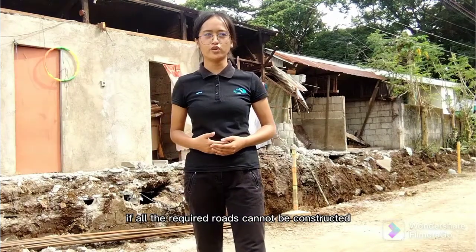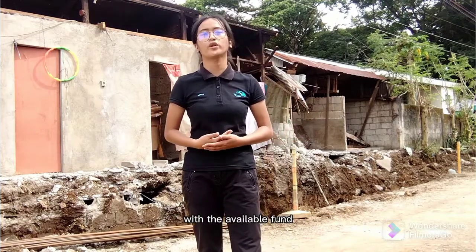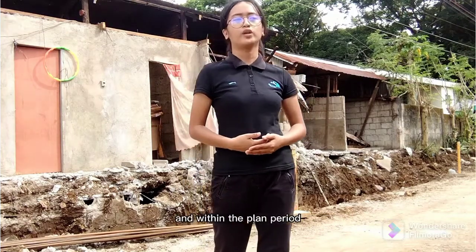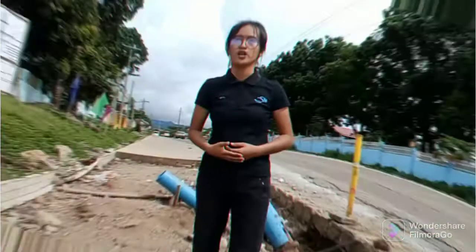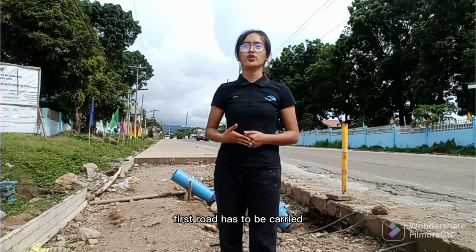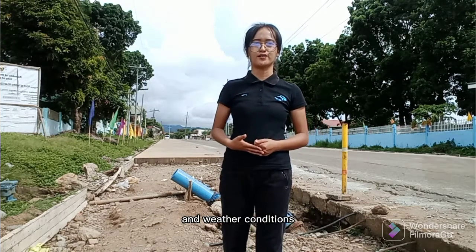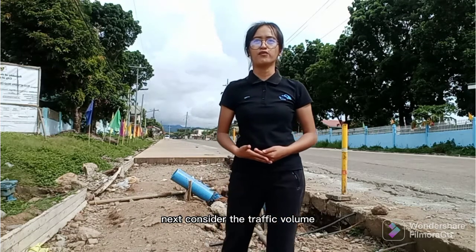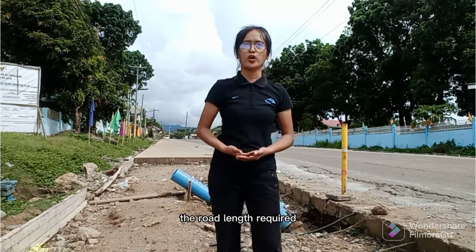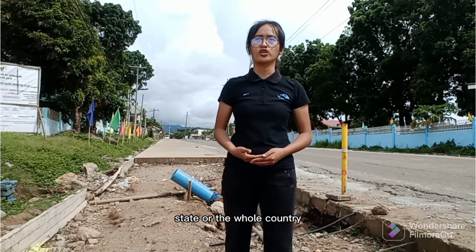If all the required roads cannot be constructed, the most important should be constructed first with the available plan and within the plan period. So, these are the following important notes to remember. First, roads have to be carried out according to the different season and weather conditions. Next, consider the traffic volume, road transported, location, function, etc. The road length required for an area, it may be district, state, or the whole country.